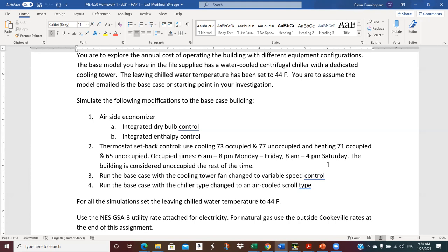What that's referring to is we have to make a decision. Do we want to minimize our outside air or do we want to maximize our outside air? It has to do with the energy content of the return versus the outside. In a cooling situation, whichever one has less energy, we want more of, because it's less mechanical cooling, less energy cost. Well, how are you going to make that determination? You have to compare something in the return air with the outside air.